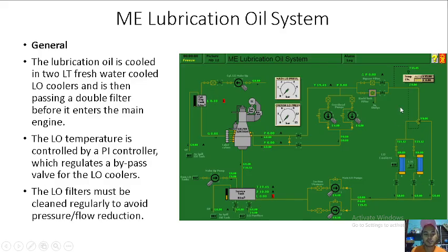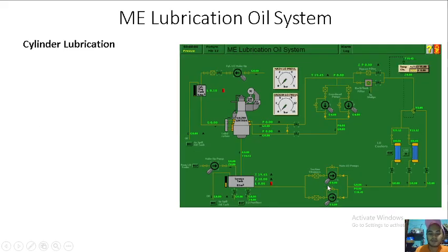So the lube oil filter must be cleaned regularly to avoid pressure reduction or flow reduction. Usually this will be cleaned every arrival at port if the engine is stopped. Or you can still clean it if this one is running, you can clean the standby filter.